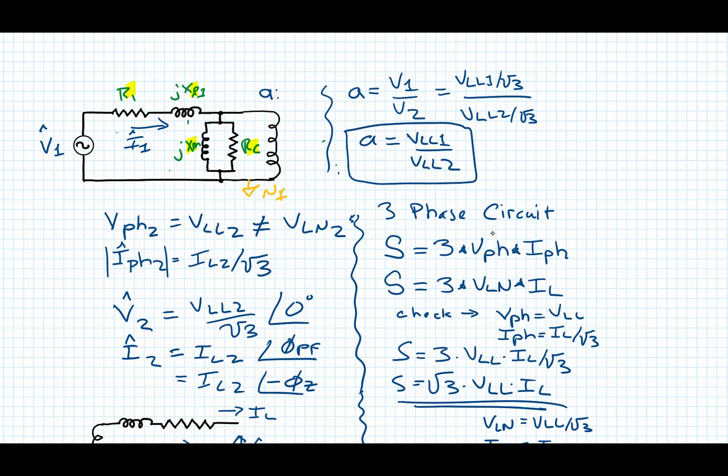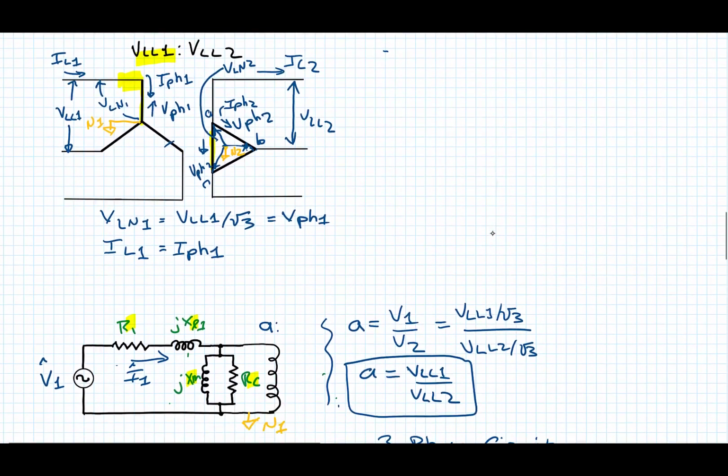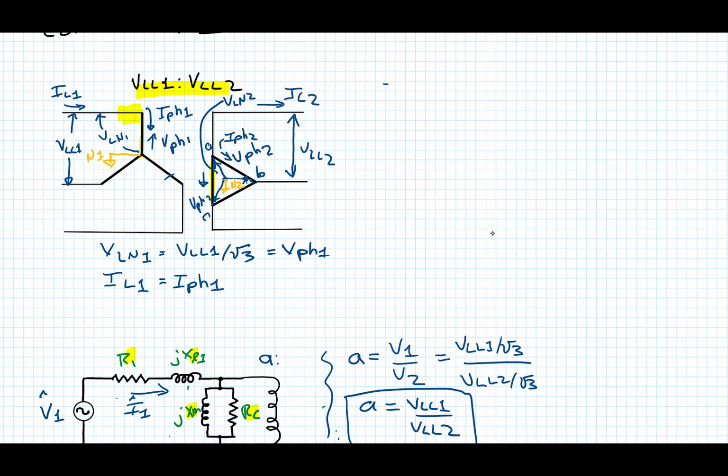So this is very helpful because it tells us another way of looking at how useful it is to express things this way. What we're really saying is that this is for each line to neutral phase, and it may not be physically realizable. It won't be if there's a delta, but it's going to be A to 1 still, where A equals the ratios of these.